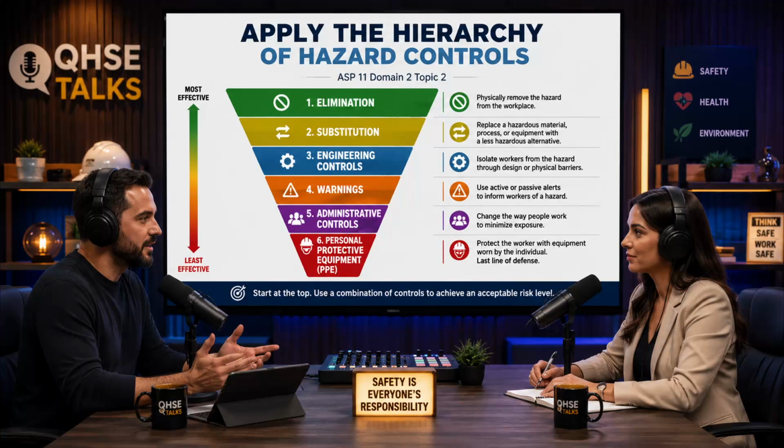An interlock is a mechanism where the physical guard is electronically tied into the machine's power circuit. If a worker attempts to open the guard door to reach into the dangerous pinch point or cutting zone, the interlock immediately severs the power. Yes, bringing the machine to a dead stop before the human hand can even reach the hazard. The barrier isn't just a piece of plastic. It is a designed mechanical response to human interaction.